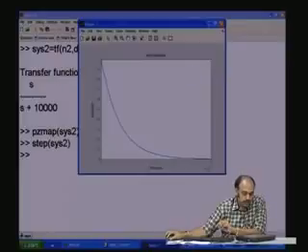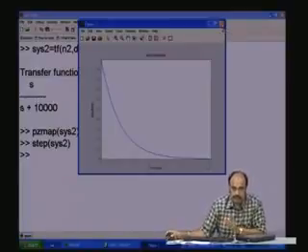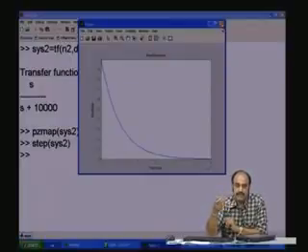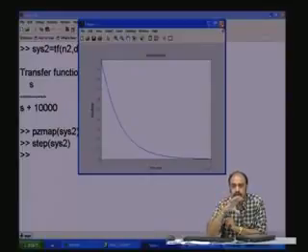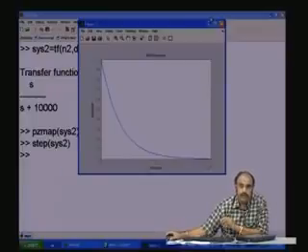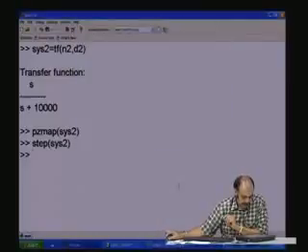Now, let us see both together. Transfer functions are single input, single output systems. They can be defined only for one input, one output. The numerator is a Vi or a Vs or a Vr or any other parameter or a current, and the denominator is another variable. You cannot have multiple outputs, you have to look at them separately. But in the case of the state equation, I can have multiple inputs, multiple outputs, you can look at many outputs simultaneously. So, let us see simultaneously both the outputs.